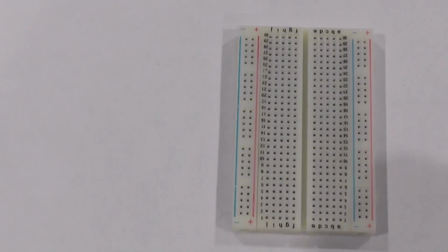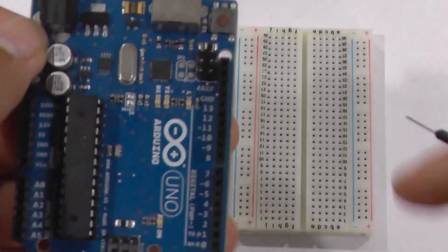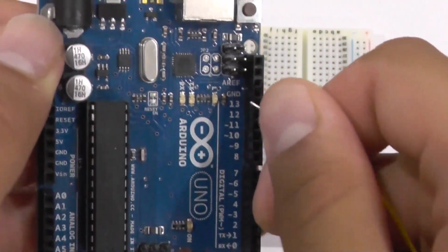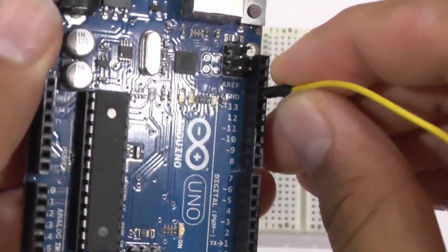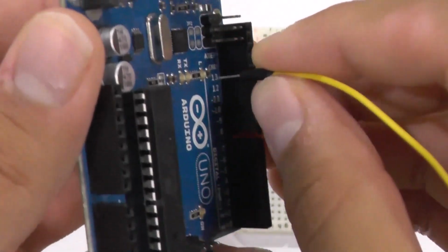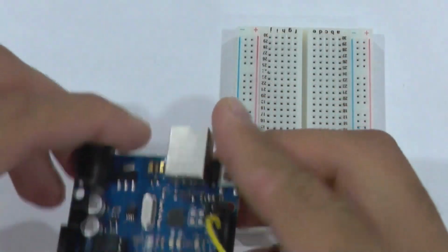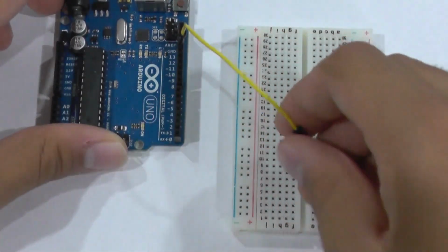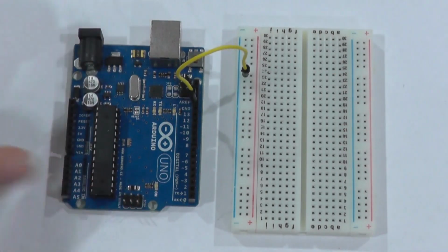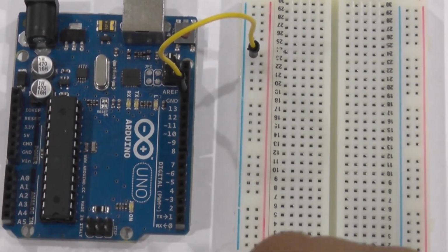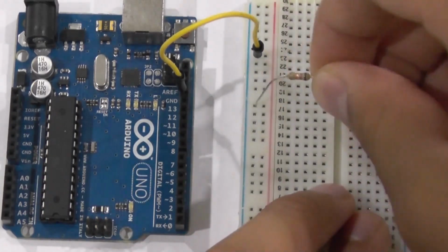You need to set up a ground pin. So you do that by plugging in the jumper cable into the ground pin of the Arduino board. You can do that by just lining them up to make sure you're plugged into the right part. Then you plug in the other side to the negative rail of the breadboard. Next, you plug in one leg of the resistor into the negative rail, then the other leg across from it into any other of the rails.